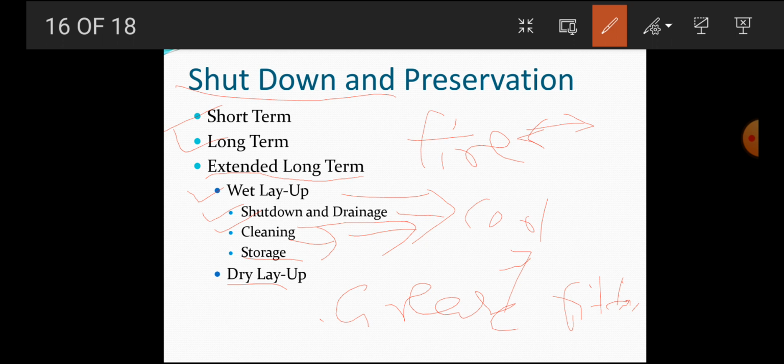Fill boiler to top with water, adding required amount of water treatment and oxygen scavenger. Then fire boiler and heat water in boiler for 2 hours to remove the trapped oxygen. So these are the steps under storage.